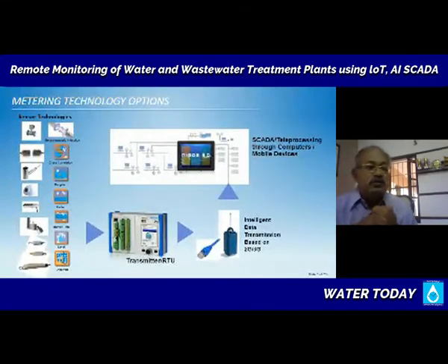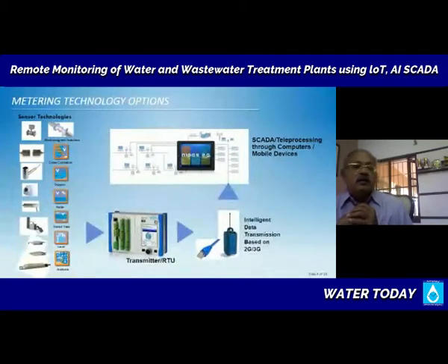So there is a wide range of sensor technology. The reason I wanted to show this to you is you may face water flow applications where you would use electromagnetic. Electromagnetic is a very rugged, robust, long-lasting device, but it is not suitable for all applications. As we discussed, it's not suitable for very low velocities. Sometimes you have to drop the pipe diameter. If you want to measure in a 300 dia pipe, you may reduce the diameter to 200 to make sure that the pipe is full of water. Now the trouble is, the moment you reduce the diameter of the pipe, you have created a pressure drop in the system. And that pressure drop will always remain throughout the life of the system.